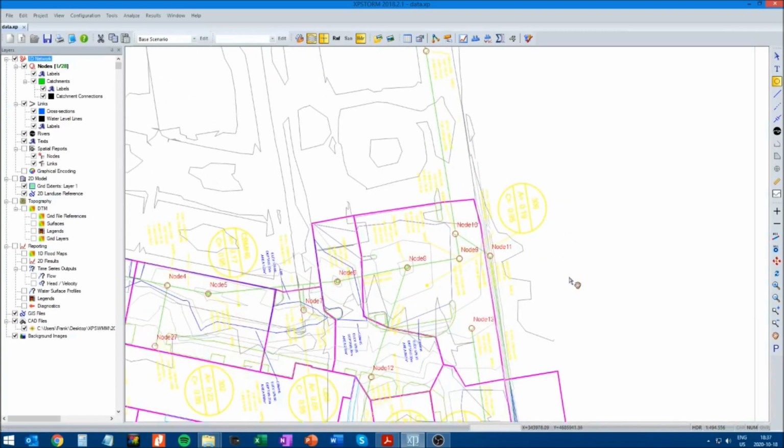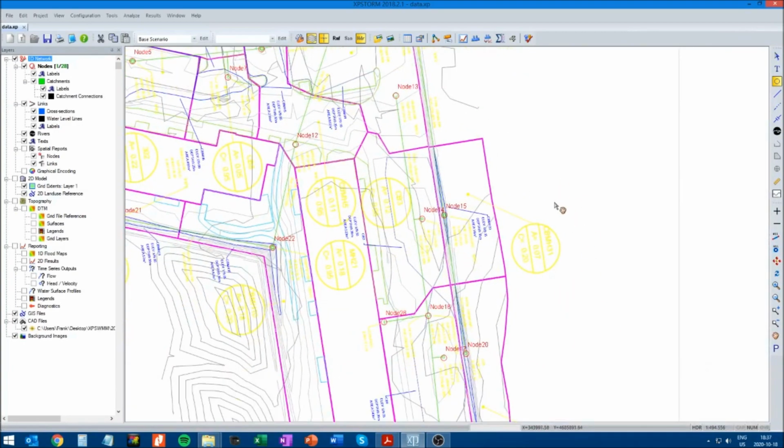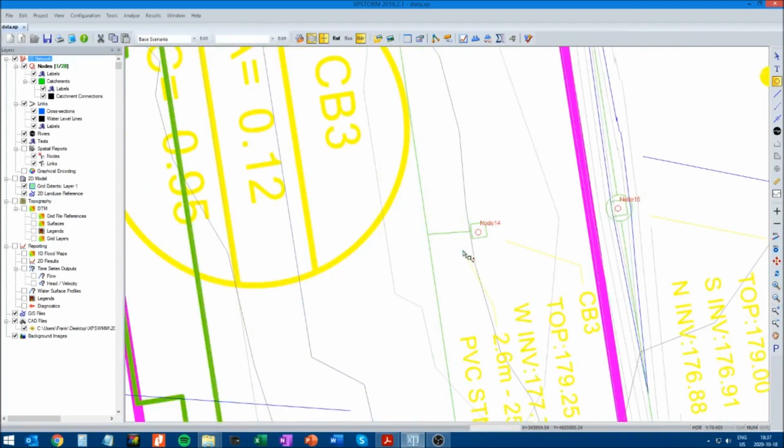Another thing I'm going to do is for all the blind connections, meaning any connection where a catch basin connects to the main pipe, not through a manhole but directly to the pipe, I'll set those up as nodes, because it makes the system more realistic, and we can then set up the inverts at that junction directly. So we'll again pick the node icon, and where there's a blind connection we'll put a node.